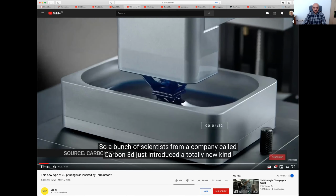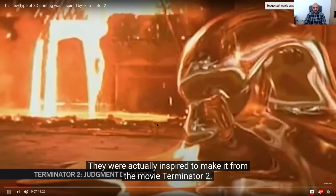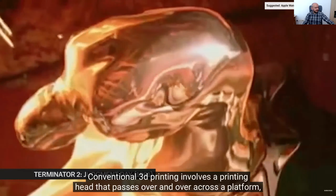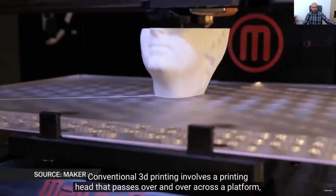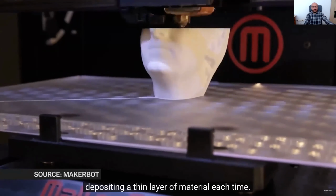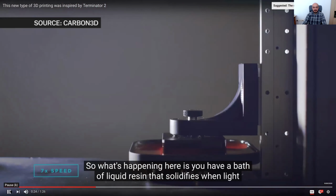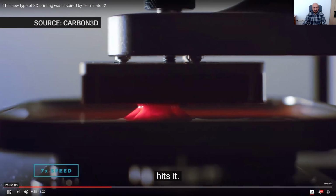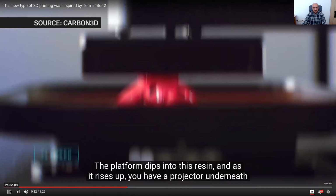Company called Carbon 3D just introduced a totally new kind of 3D printing. They were actually inspired to make it from the movie Terminator 2. Conventional 3D printing involves a printing head that passes over and over across a platform, depositing a thin layer of material each time. And this 3D printing forms an object continuously out of a liquid resin. So what's happening here is you have a bath of liquid resin that solidifies when the light hits it. So the platform dips into this resin, and as it rises up, you have a projector underneath the resin pool that's projecting a series of